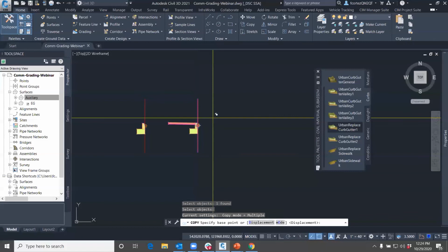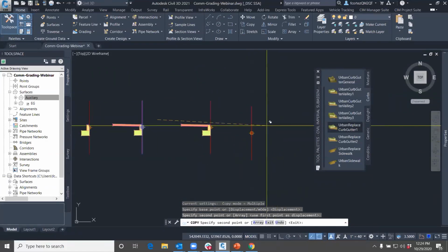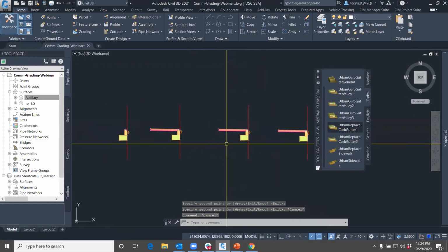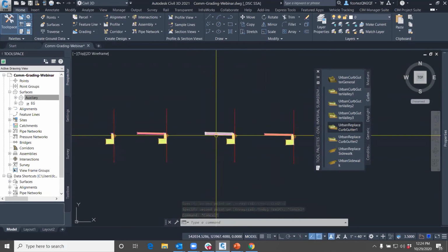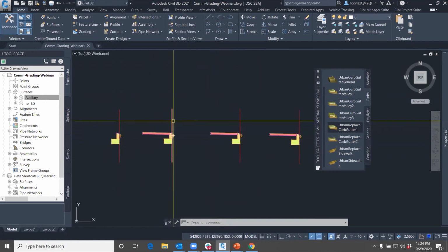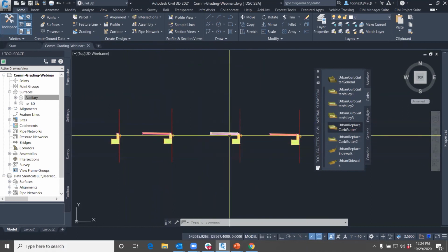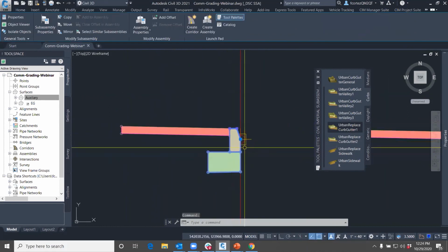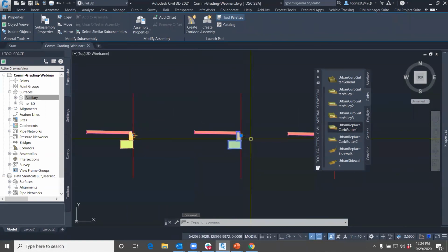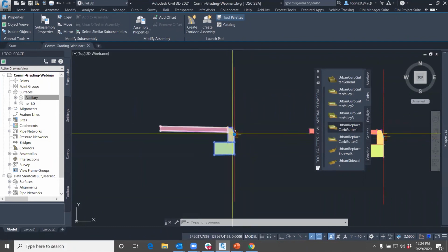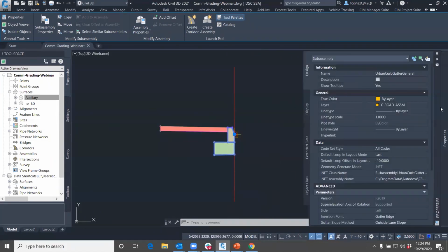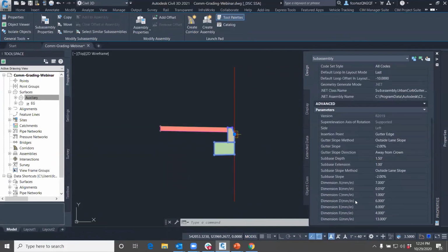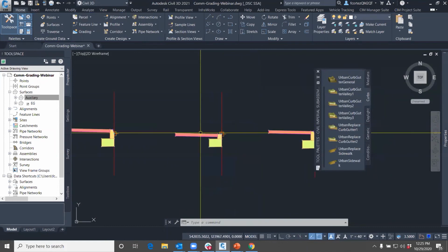And we're going to need a 4th one. What we're going to need this 4th one for is, we're going to have a curb and a curb with the sidewalk. And what we're going to have is a curb, but we're going to want to create a landing for our ADA ramp. So what I've found to be the easiest is to go ahead and make this a 0 height curb. So I'll go here to my dimension D, make this 0.01, since we can't make it a 0, and then you just got to adjust the backside to 7 inches. There will need to be a sidewalk.